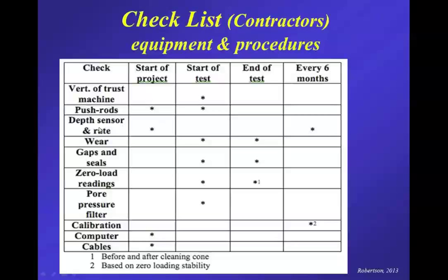And a good practice for depth is to also do a rod count. So let's say you're going to push 50 meters. Just get the operator to count the rods. And so if you push exactly 50 meters on the depth sensor, just double check that you pushed exactly 50 meters of rods, that you didn't accumulate or lose any depth through either inaccuracy of the sensor or the sensor missing a few readings, etc.